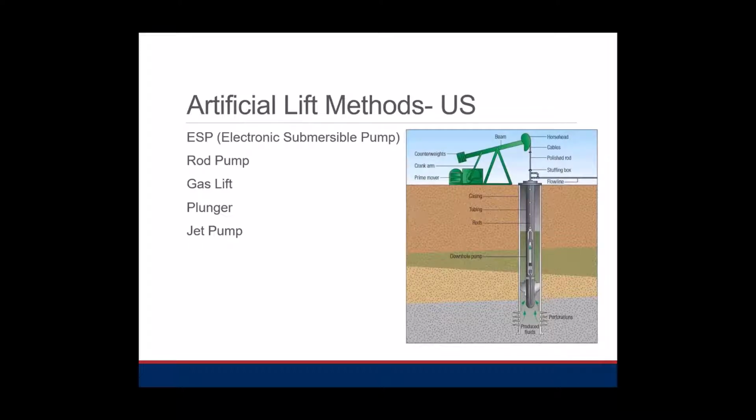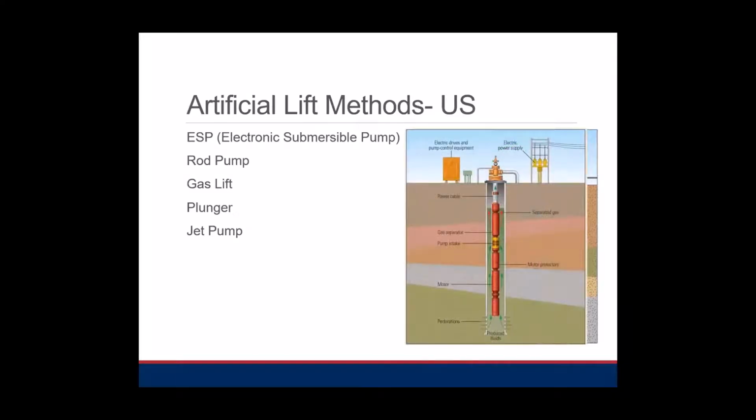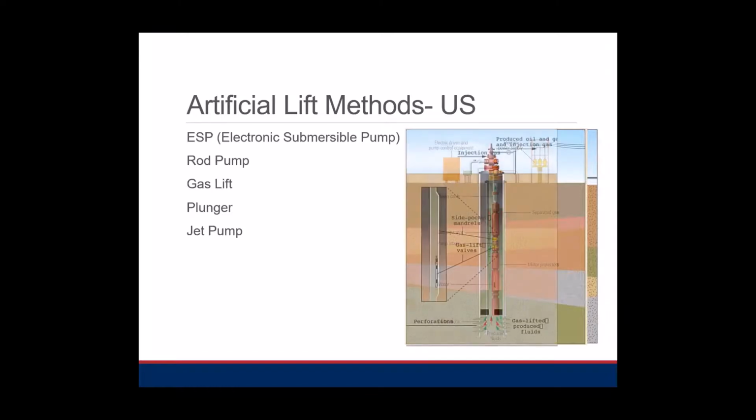Downhole pumps don't like gas. Gas is fairly compressible, whereas a fluid is not compressible. So the whole system loses efficiency if gas is in that system. Same thing with an ESP. An ESP is an electric submersible pump. It's a series of motors that spin a pump, and on those they have gas separators as well. They're used in a higher volume type well.